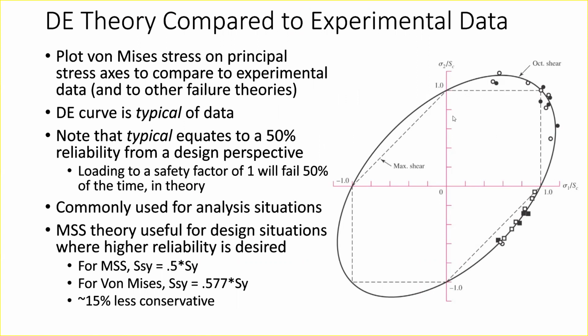So it's less conservative than the shear stress case. So it tends to predict part failure pretty well. And this is kind of the standard for most parts. Again, if you're dealing with a super unique part that's extremely brittle, you might refer to a different failure theory. But in general, most metals that you work with that are relatively elastic, somewhat ductile, like steel, aluminum, are going to be really good for this theory. So FEA is going to be a pretty good approximation for most parts that you make on a car.